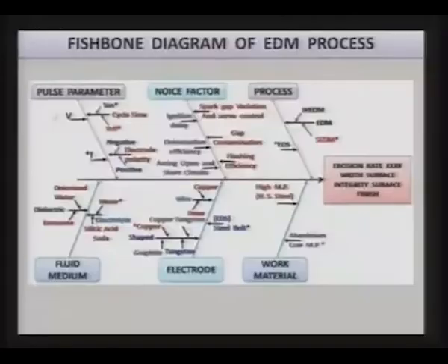We can use the deionized water as the dielectric, but there are various kinds of oils that are used as the dielectric, mainly kerosene is one of them most commonly used. Then there is the electrode, you can use the copper as the electrode material, and when you are using wire EDM, as we are going to discuss shortly, then there you can use copper wire as the electrode.